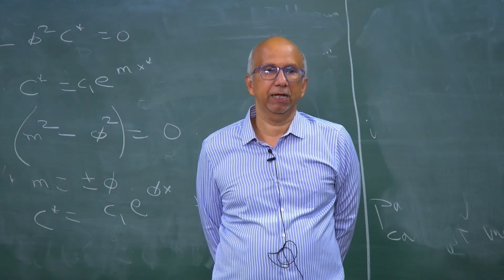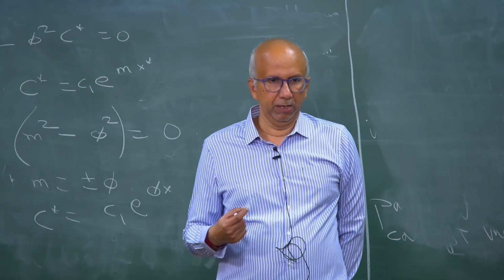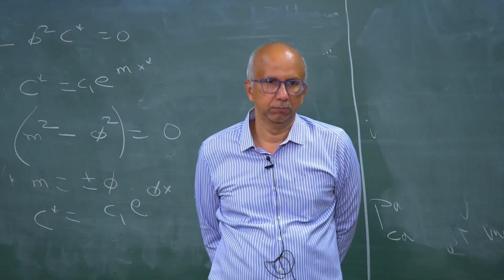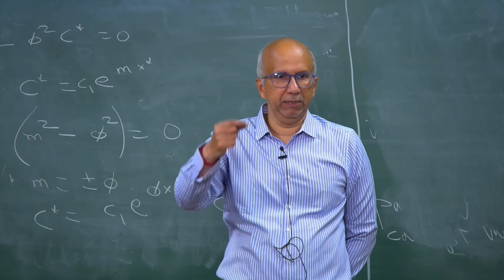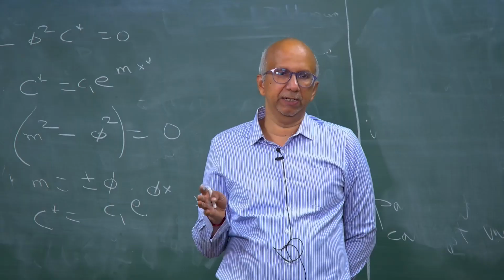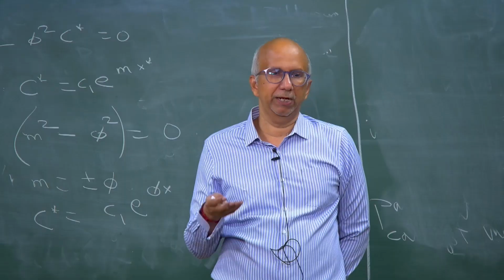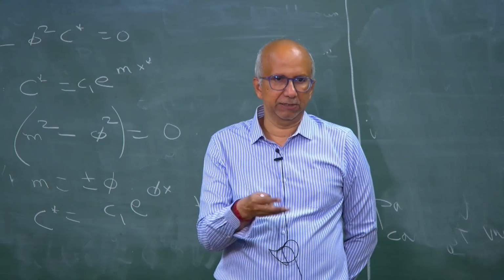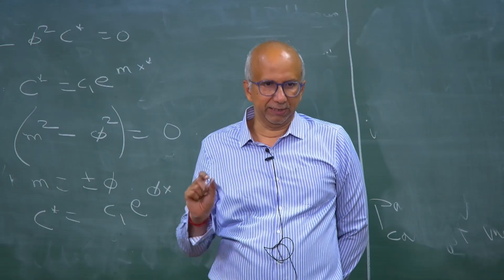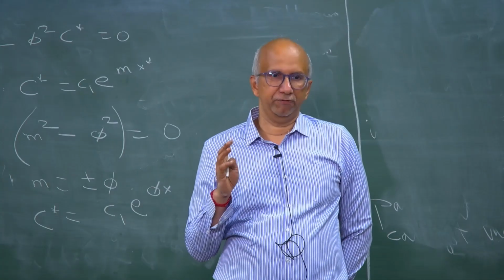Therefore, even if you put catalyst somewhere in the middle of the pellet, the concentration of the reactant in the center is going to be 0, because it got consumed near the surface. So towards the center, it is not contributing to the reaction. Any precious metal you are putting there is a waste. When you do your synthesis of the catalyst, you should synthesize it so that the catalyst is only on the surface.